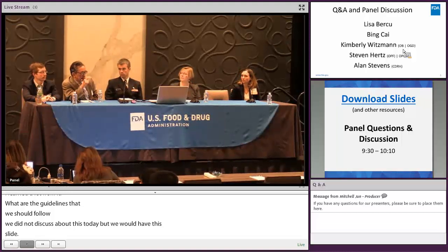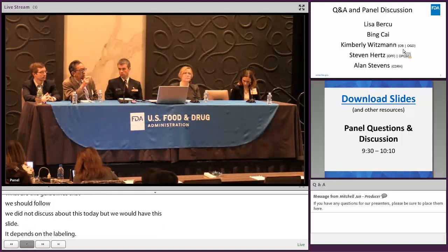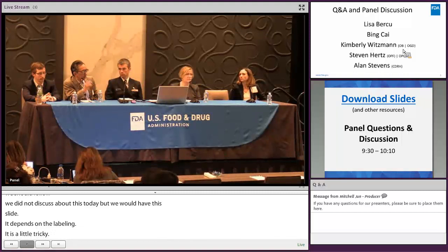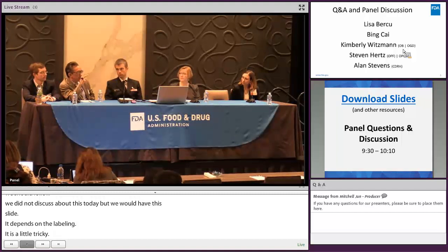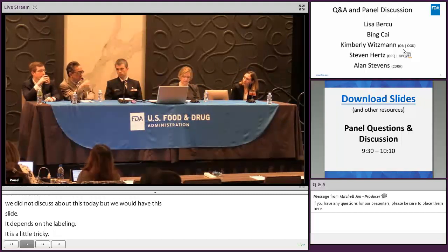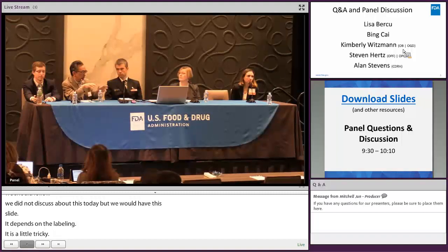In the prefilled syringe, there's some dead space, so you have to consider that. In your product development, you say you want to include a certain overfill. This overfill can compensate for the dead space, as well as for cases where the label says the patient or caregiver needs to prime the syringe a little bit, a couple of drops. You have to consider all of this, and then you can propose your overfill for a prefilled syringe. Okay.